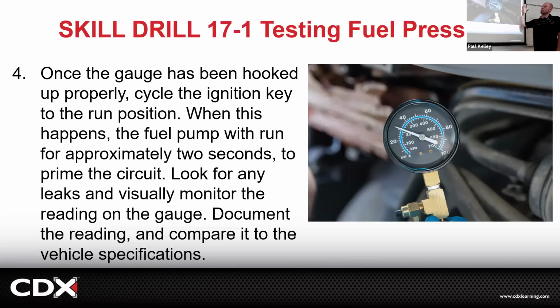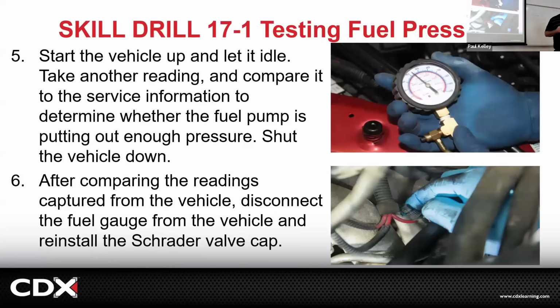But if you start to see your fuel pressure dropping and it's correlating with the stumbling and then ultimately the stalling when it hits zero, you'd be like, oh yeah, it lost fuel pressure. Now the question is, is it electrically the fuel pump itself? Or could it be a wire going to the fuel pump or the relay that powers the fuel pump? Then you're just diagnosing an electrical problem, right? So sometimes these drivability and engine performance problems are some of the more complex. But if you can understand it, you could definitely fix it. But it is a bit of a more challenging subject, right?